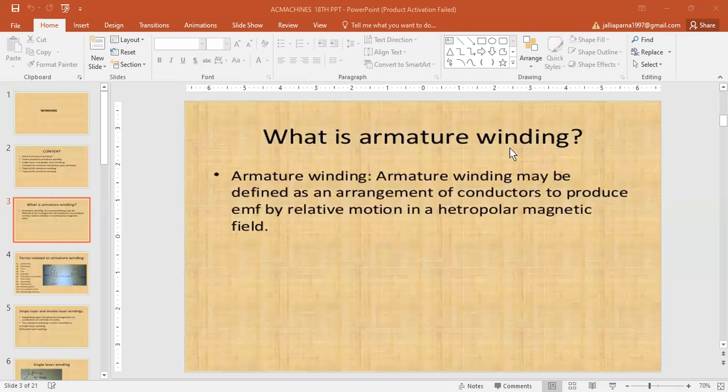It means that the coil span is 180 electrical degrees. In this case, the coil sides lie under opposite poles, hence the induced EMFs in them are additive. Therefore, maximum EMF is induced in the coil as a whole, it being the sum of the EMFs induced in the two coil sides.